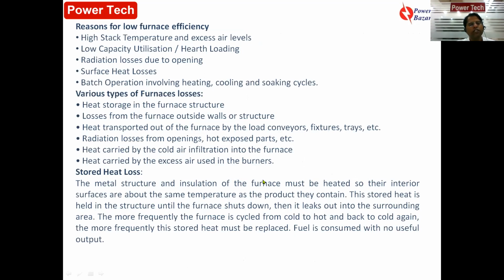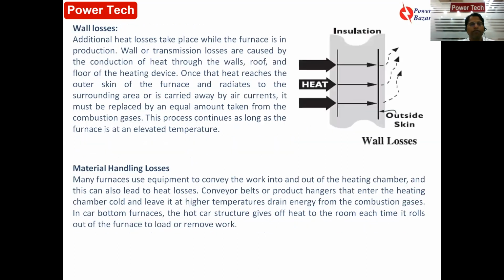This heat energy is stored as long as the furnace operates. Now if the furnace goes for a breakdown or shutdown, what will happen? This stored energy gets released to the atmosphere during the cooling process. So there is a loss of stored heat during cooling time or furnace downtime. So these are known as stored heat loss.